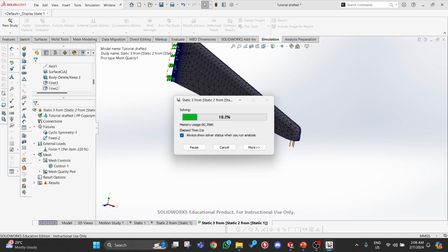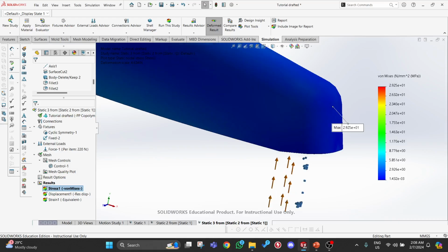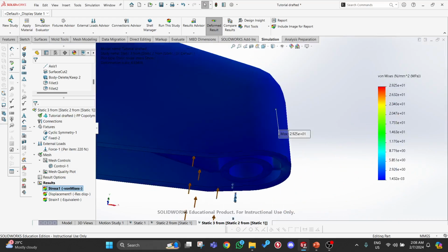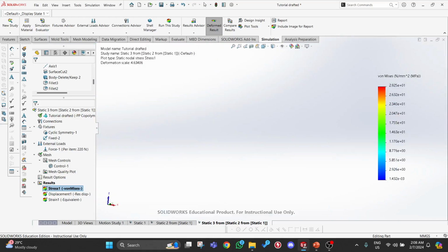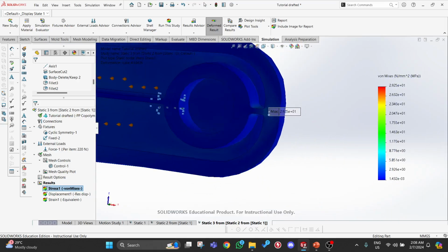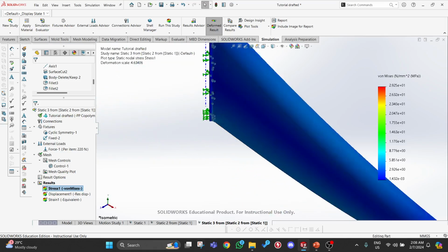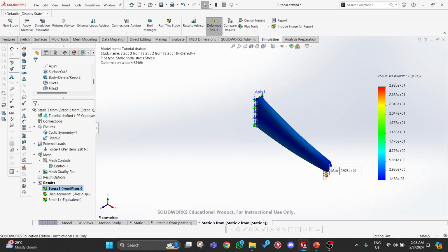And you just learn local mesh refinement and learn how to use FEA analysis to your benefit. Unfortunately, I couldn't get the value right for this case, right? Unfortunate, but it is what it is. And you can see this part is still the issue. It's getting worse and worse, and somehow and somewhere there is an issue here that is causing the stress level to go very, very high, right? Even though the rest of the part should be okay.